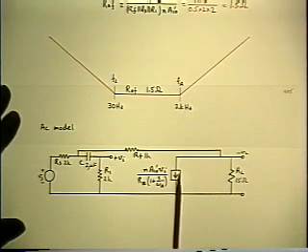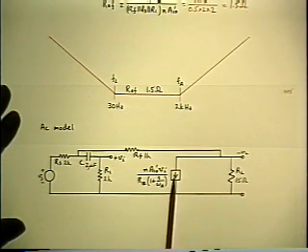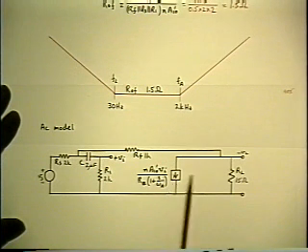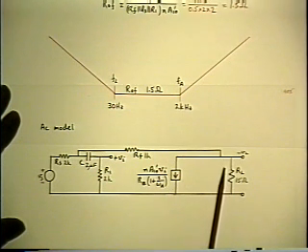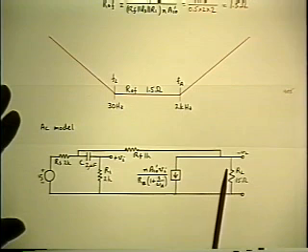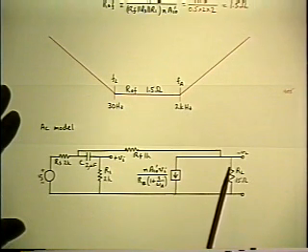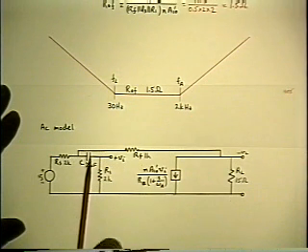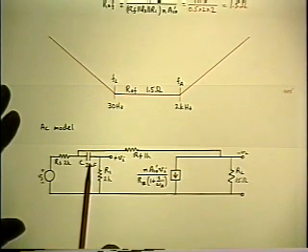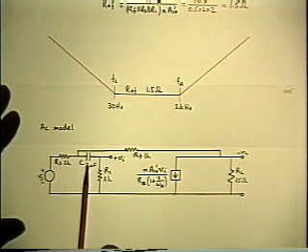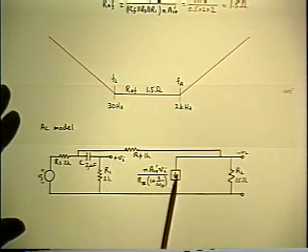Well, this current generator would be inactive at very low frequencies because when we apply the test signal at the output in order to determine the output impedance, the Vs would be 0 and the test signal we apply would go down the feedback path, but this coupling capacitor would be open at very low frequencies, so there wouldn't be any Vi, so this generator would not be activated.